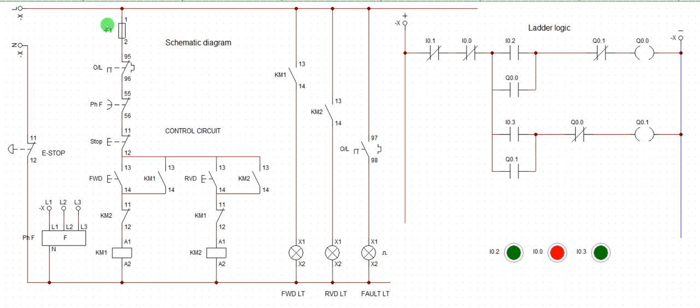Now here, this particular network is going to represent the whole of this logic. The whole of this logic that I have here is what I represent with this network. Okay, this is my overload. All right, and this is my normally closed bit. This is also my normally closed bit. This one open here is normally open bit. Okay, so this is how you recognize normally open and normally close.